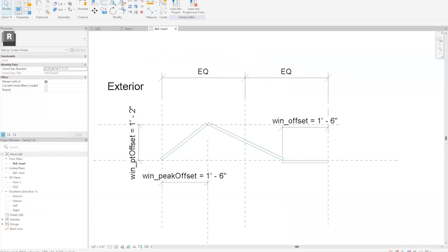Yeah, and I can qualify that. Are you looking to schedule each individual part? Then they're going to have to be a nested shared family that you can actually access. Or are you just trying to dump the geometry in, maybe with a little bit of information that you could schedule or get quantities from and tag for coordination purposes? Or are you trying to build something more complex? You have options to do both, for sure. So the answer is it depends. Exactly.